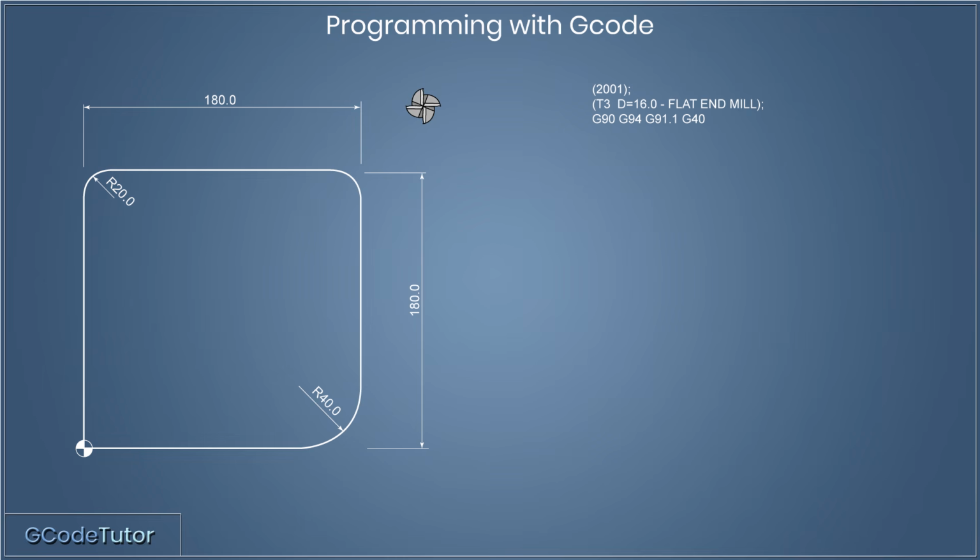Now this safety line is normally the most complex part of the program to initially understand when you're new to G-code programming. But it's okay, you can always copy and paste this line until you understand fully what each G-code means. Next up we have G49. Now G49 is tool length compensation cancel. It cancels any offsets in the tool length. Tool length offsets are very important because they tell the machine how long the tool is and where the exact tip of the tool lies in the 3D environment. But this line just cancels any offsets that may be active, so we can start afresh.